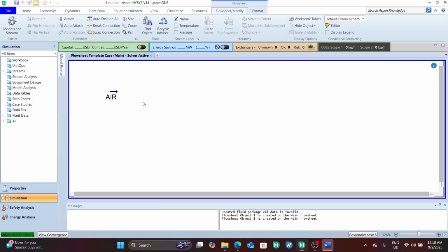So we are expected to carry out two opposite actions: compression, which raises our temperature, and cooling, which drops the temperature. Based on research, we need a pressure of around 6 to 8 bar, but we will be working with the high end, 8 bar, for our cryogenic distillation. We need to be at around 8 bar before we go inside the distillation column, and at a temperature between negative 160 and negative 185.